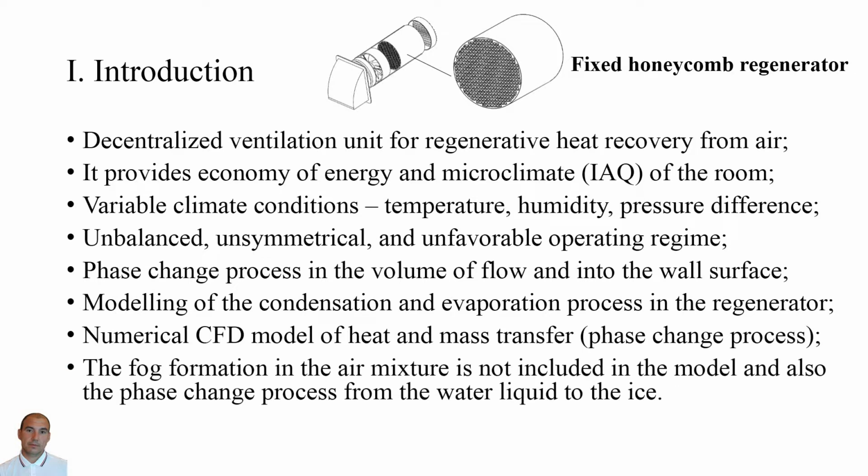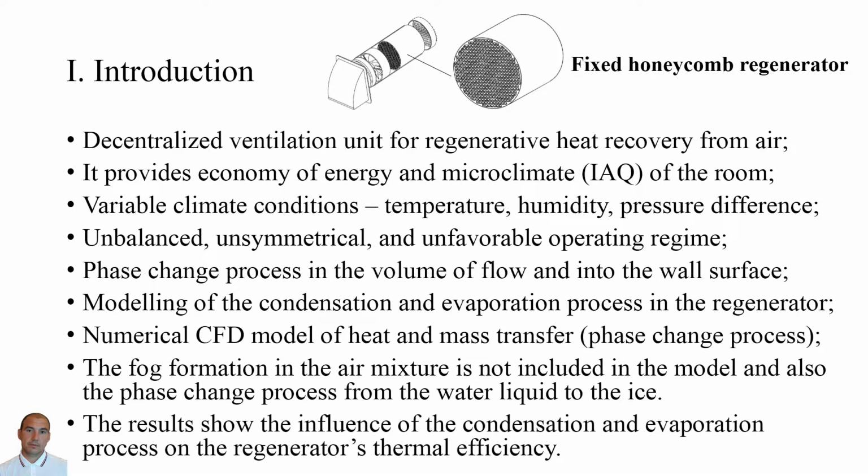The fog formation in the mixture flow is not included, but the existence of supersaturated vapor in the airflow is presented through the parameter values of relative humidity. And also the phase change process from liquid water to ice is not included in the model. The result shows the influence of the condensation and evaporation process on the regenerator's thermal efficiency.